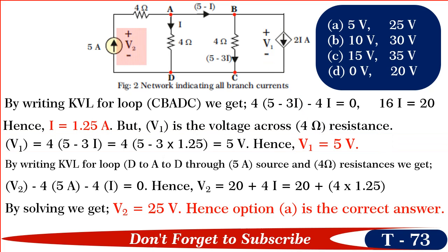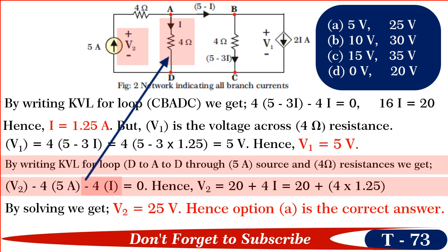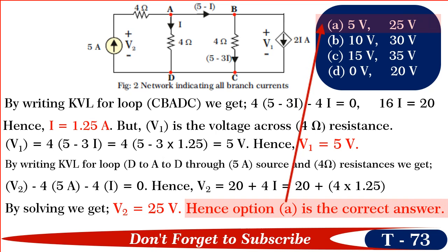To find V2, by writing KVL for loop D to A to D through 5 ampere source and 4 ohm resistances, we get V2 minus 4 into 5 amperes minus 4I is equal to 0. By substituting I is equal to 1.25 amperes and solving, we get V2 is equal to 25 volts. Hence, option A is the correct answer.